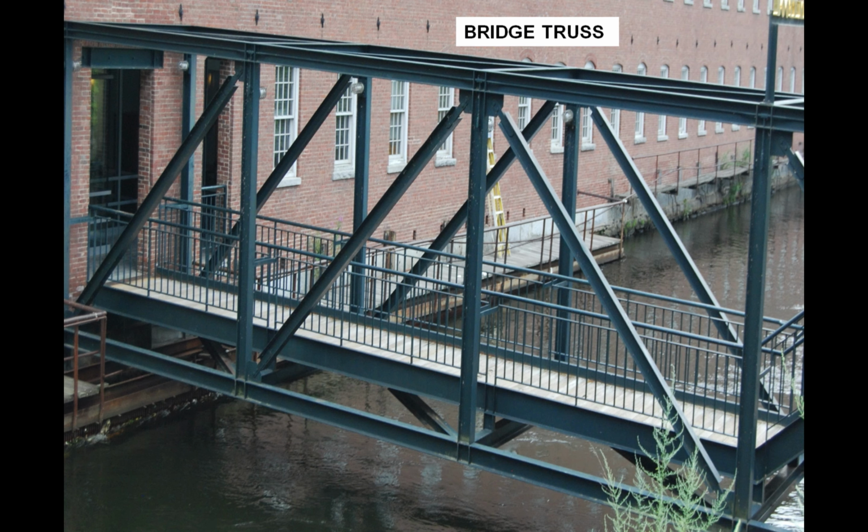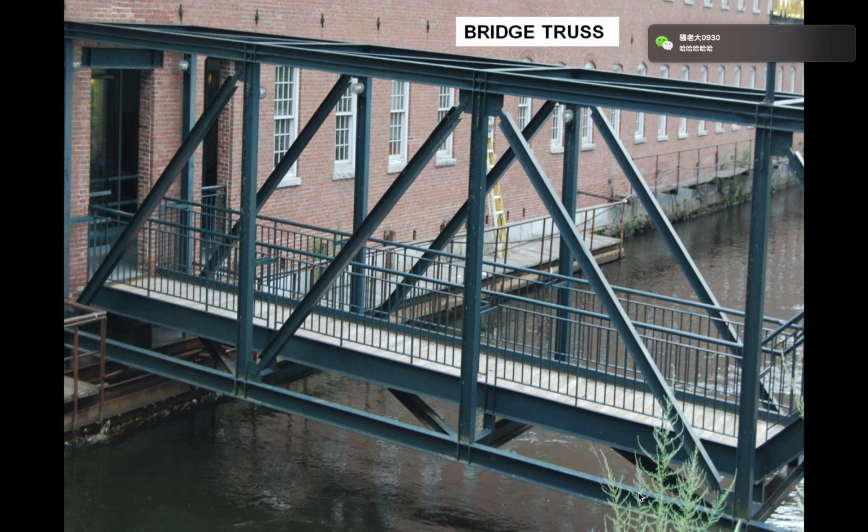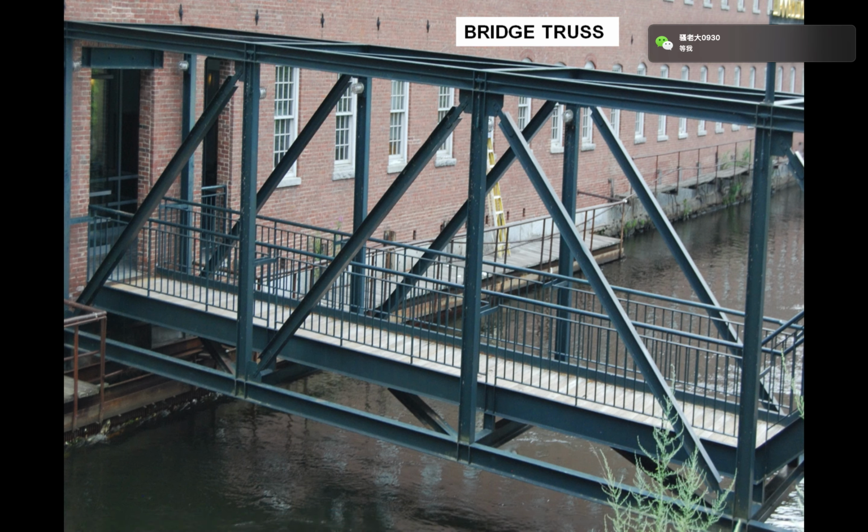I think everyone has seen a triangular patterned steel structure. And there's a number of different truss types based on the engineering founder who developed them, from a Pratt truss to a Warren truss. But basically, the key there is they're all in the form of what's really one of the structural shapes, which is a triangle. Right, so basically every truss is a combination of triangles which hold together a larger structure.